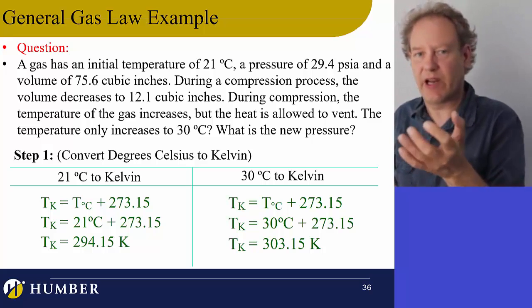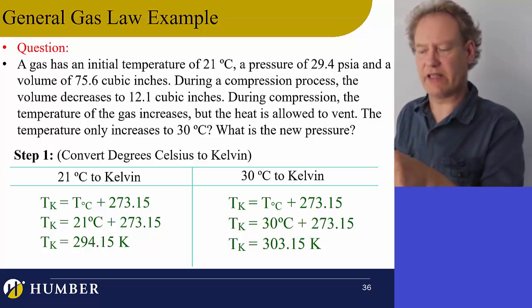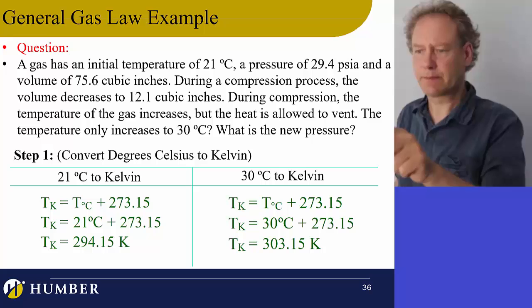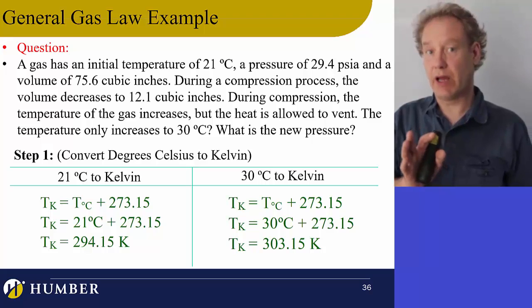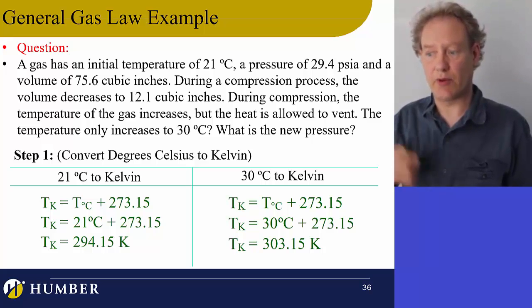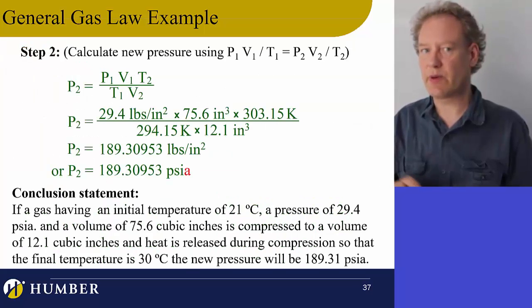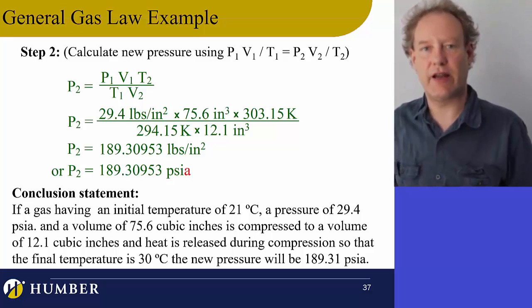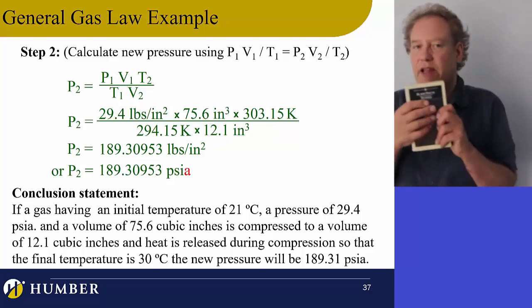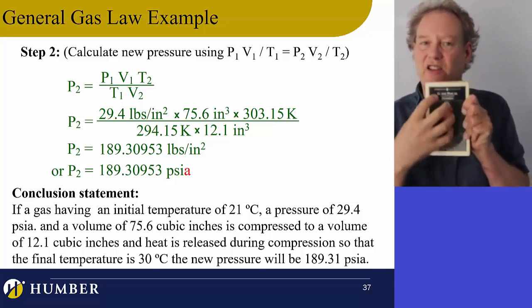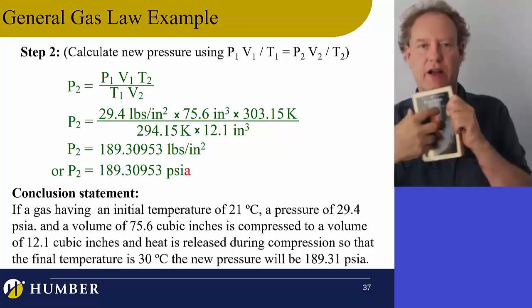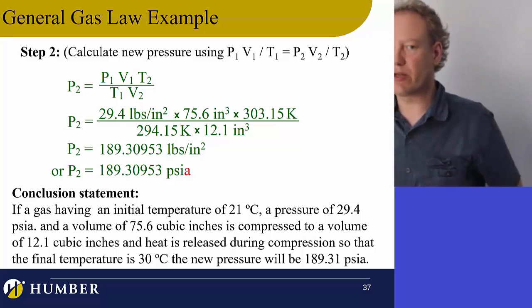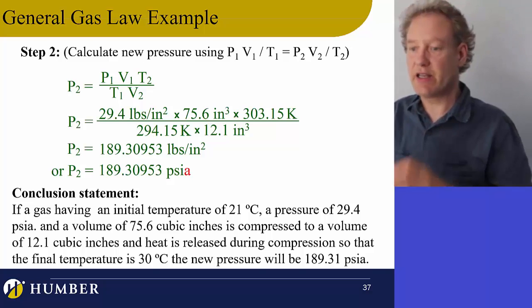So you'd think the pressure would go up by 6 times. Well, okay, so 176 psiA is 6 times 29.4. So if I took 29.4 psi and increased that pressure by 6 times, I'd end up with 176 psiA. But look at the pressure. It's a little bit more than that. It's 189, and the reason is because we've left heat energy inside. Some of that extra heat energy is making the molecules hit the surface with a little bit more energy packed in. The density of that energy is greater in any particular area. So that increases the pressure. So that's what's going on. So that's the whole thing.